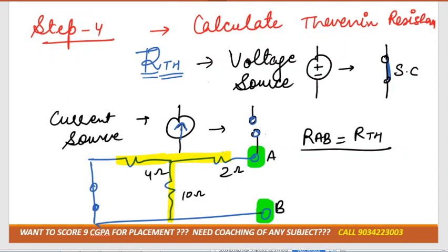And if two of your friends are on different paths, then they are connected in parallel. We'll start from those which are very far away from your house, like from A and B. So 4 ohm will start. 4 ohm and 10 ohm are connected at different paths, so we can do 4 parallel 10, right?